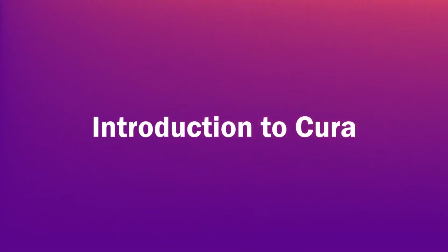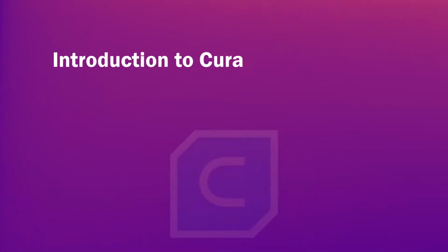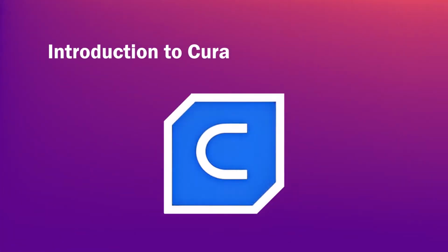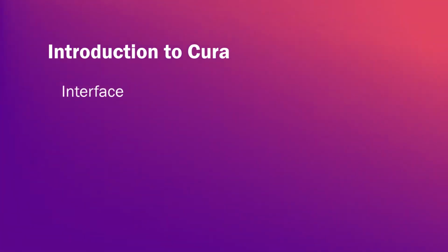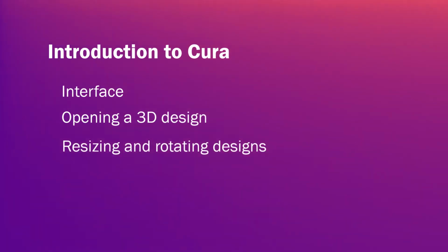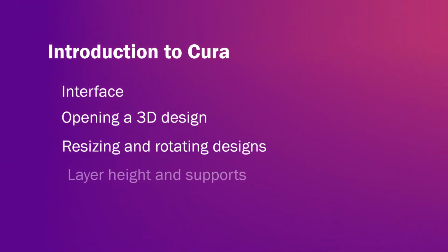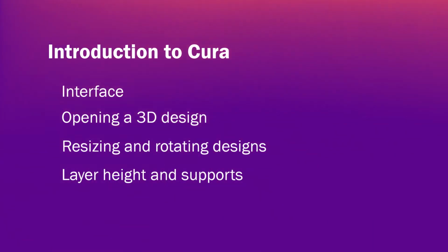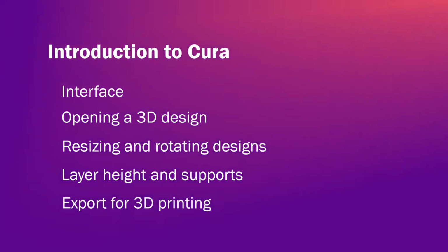Introduction to Cura. This video will be a live demonstration of Cura, a software application that prepares or slices a 3D model for a 3D printer. We'll look at the interface, opening a 3D design, resizing and rotating designs on the build plate, and other features such as adjusting layer height and adding supports. Finally, we will export the file for 3D printing.